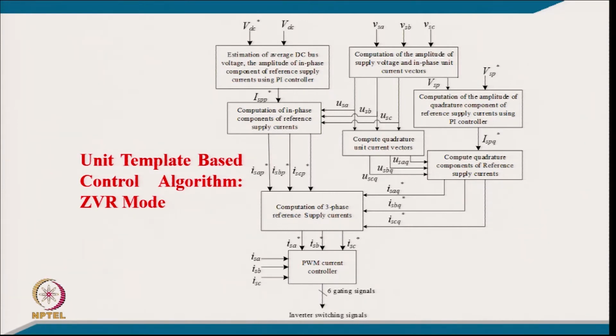So, we already have the amplitude of the load voltage, which we estimated at the point of common coupling, and the peak. We take a reference of this, which we may have as, for example, 415 volts; the peak of 415 into root 2, or we can take the phase voltage here, because it is the amplitude of the phase voltage, so it is 239 into root 2. That will be the peak, as a typical example. And then we have the estimated voltage, or the feedback, here.